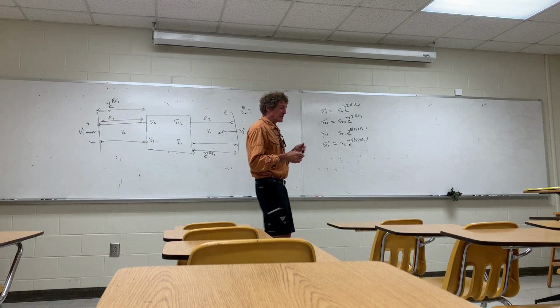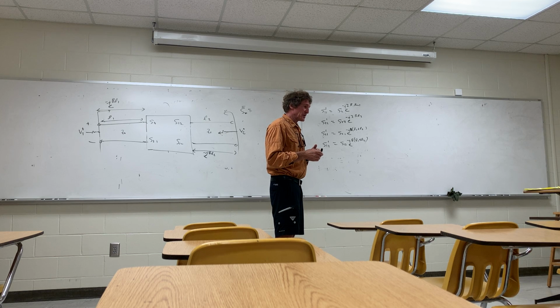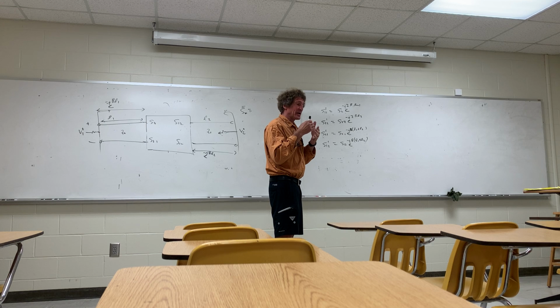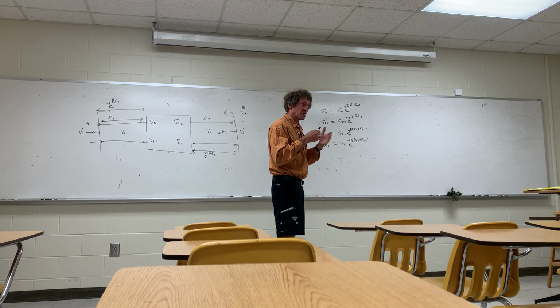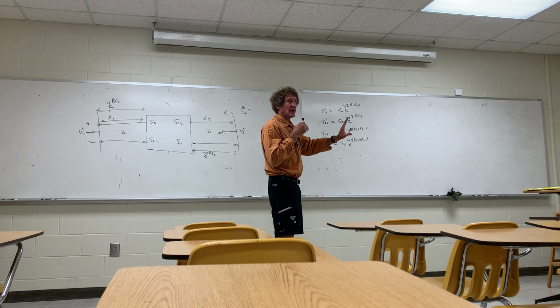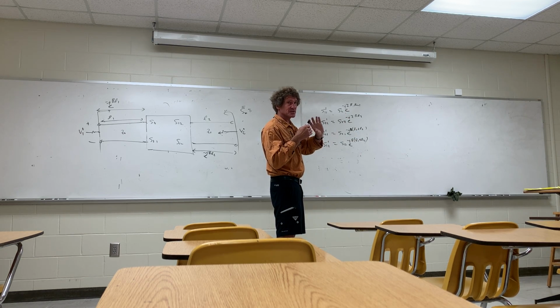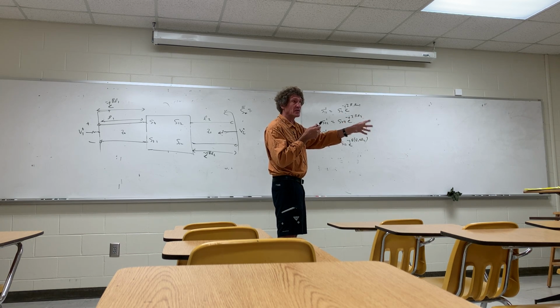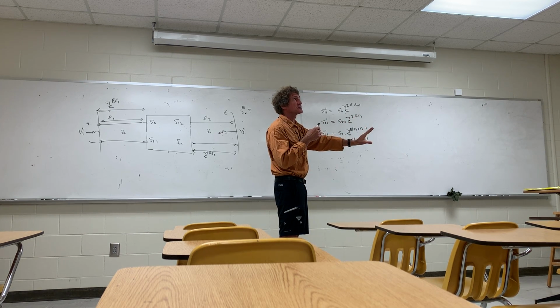And then what we had to do is use this genetic algorithm, which basically does this. It takes initial guesses of what the values of epsilon are, and it sees how close the output from those guesses is to the actual output. Then it creates a new set of guesses of epsilon based on the difference in what was actually obtained and what we guessed, or I should say, the difference in the S parameters.